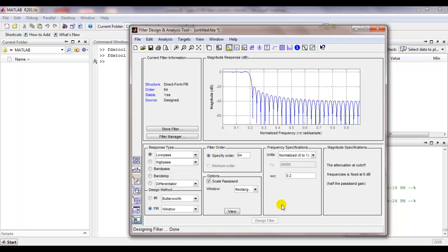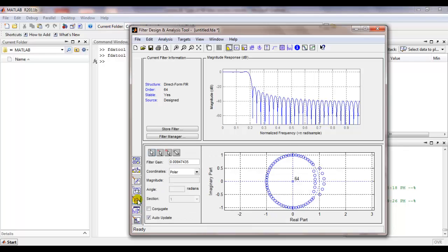All the dips that you see are precisely going to be, again, what is going to be there. If you look at the unit circle, you will see zeros there. Okay, so let's go to the pole zero plot, and this is indeed what you see. You have now 64 zeros, and most of them are meant to basically really drive down the response outside the 0.2 pi and minus 0.2 pi region. So this is what you get.